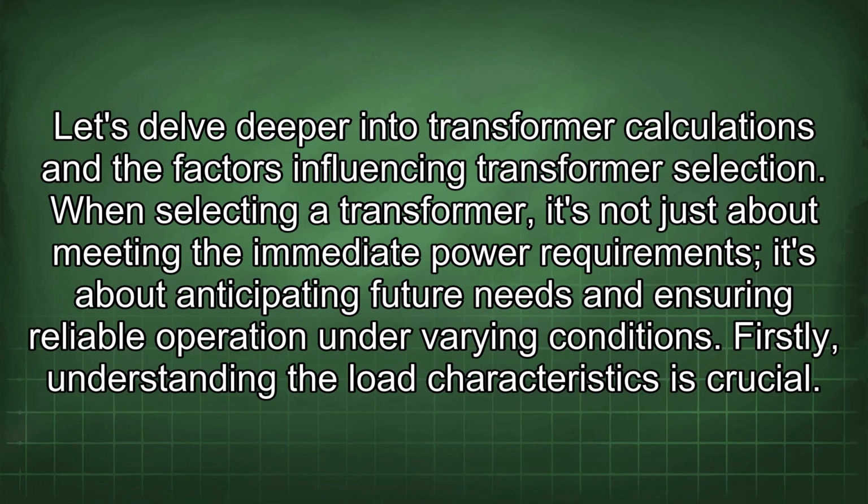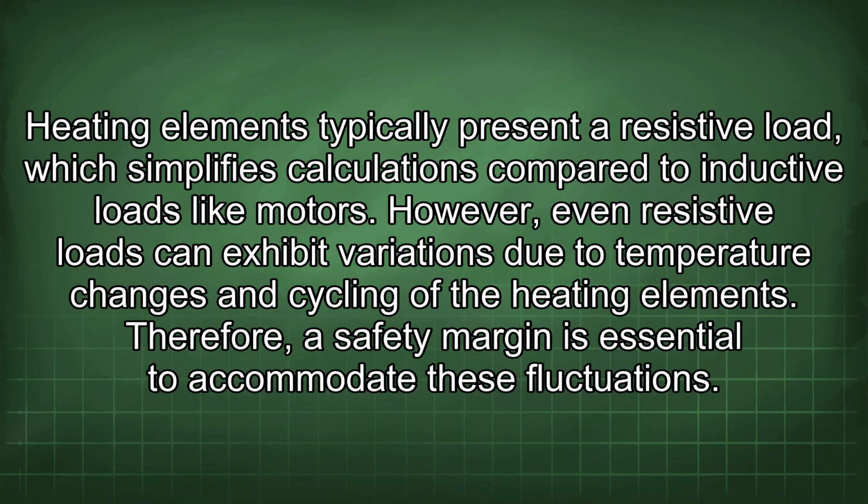Let's delve deeper into transformer calculations and the factors influencing transformer selection. When selecting a transformer, it's not just about meeting the immediate power requirements, it's about anticipating future needs and ensuring reliable operation under varying conditions. Firstly, understanding the load characteristics is crucial. Heating elements typically present a resistive load, which simplifies calculations compared to inductive loads, like motors. However, even resistive loads can exhibit variations due to temperature changes and cycling of the heating elements. Therefore, a safety margin is essential to accommodate these fluctuations.